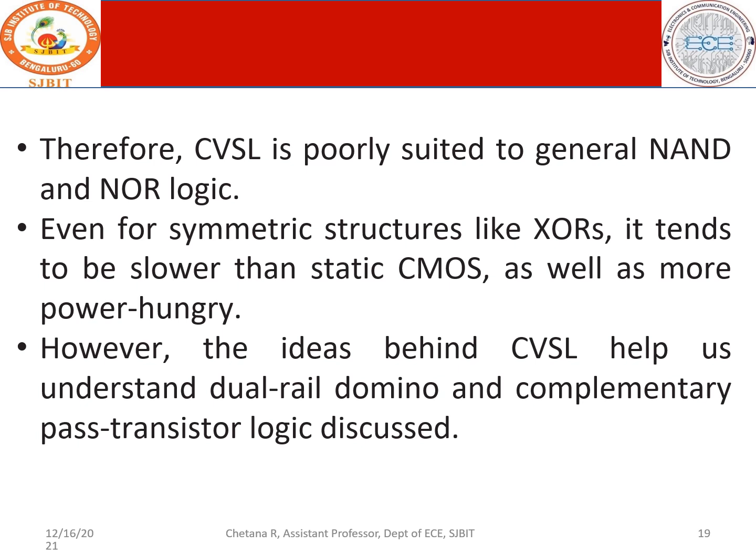So as a whole, comparing CMOS and CVSL, static CMOS takes the upper hand. However, the ideas behind CVSL help us to understand dual rail domino and complementary pass transistor logic. If you are aware of what exactly CVSL is, the next topics will be easy to understand, and that is how it helps.